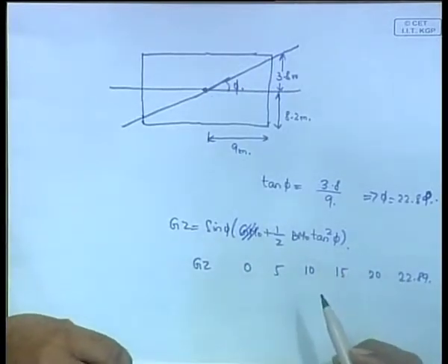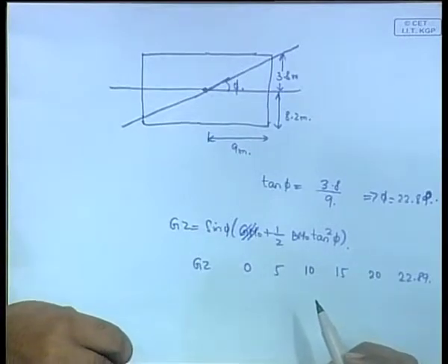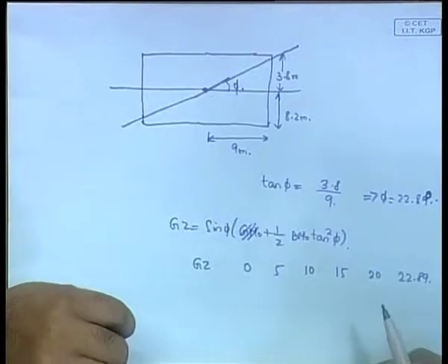So, okay, BM has to be calculated, BM, that BM again same way I by del. Okay, this is a box shaped barge. So, you know how to calculate I, you know how to calculate del. So, I by del, that is what. Once there are two, again same thing, if you are not given any information about BM, like you are not given the hydrostatic data, you have to look at the problem, means you must be given that it is a box shaped vessel, or at least that the shape of the vessel is something that you know of, some general shape, but that is not enough to calculate KM. You will be given it is a box shaped vessel, otherwise it becomes too difficult.